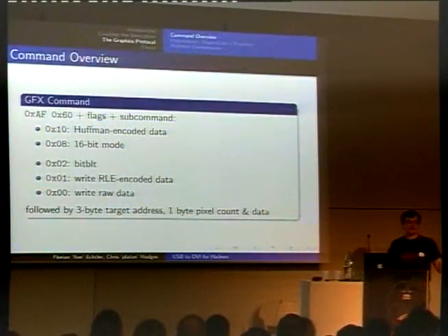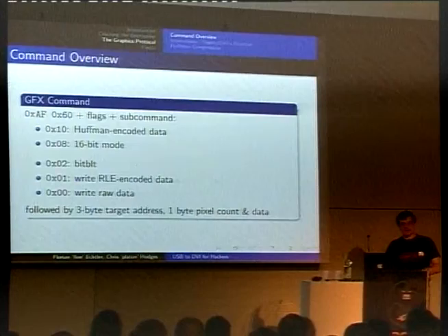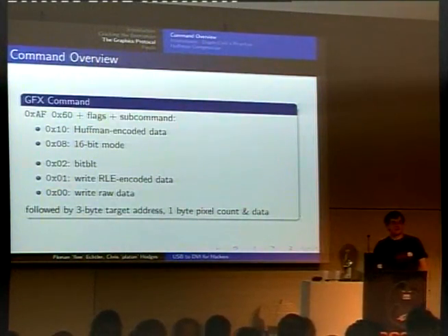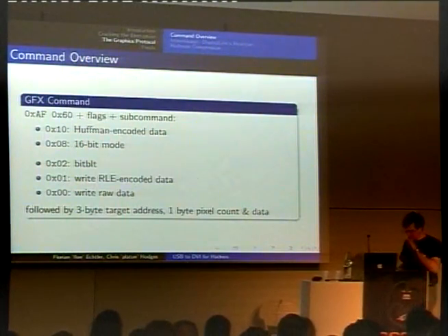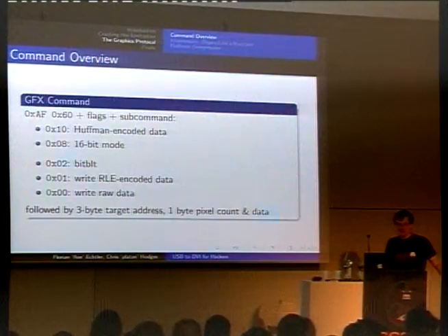So you have a 16-bit frame buffer, which is used in 16-bit color depth and in 24-bit color depth. And when you use 24-bit color depth, you get a secondary 8-bit frame buffer, which delivers the missing 8 bits of color data. Yeah, and you basically just have linear memory in the device, 60 megabytes.